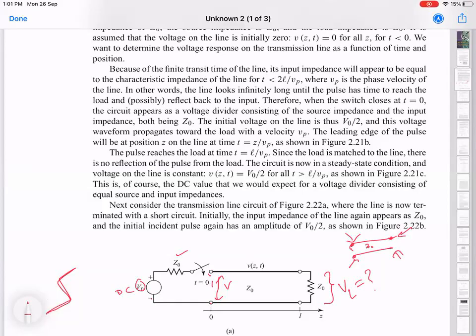Again, this is a very artificial example, but there are a few key concepts I want to burn into your memory, because I can see that some of the things I've mentioned before, because of low frequency instinct, you're saying those wrong things again. A transmission line has no meaning of a resistance along the length of the transmission line. In the ideal case, in a real transmission line there will be a resistance, but we are not talking about that. What matters is how voltage drops happen across the two terminals of the transmission line.